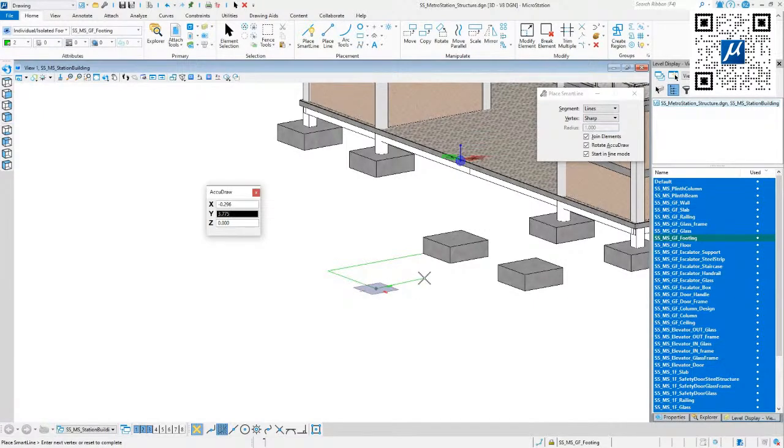Let's say we need to go up a little bit. Let's say that's an electrical wire and we have to go up to the rooftop. So I change my rotation to front view, and then I can go up. I'm using the X axis from Accudraw to go up along the Z axis of a drawing.